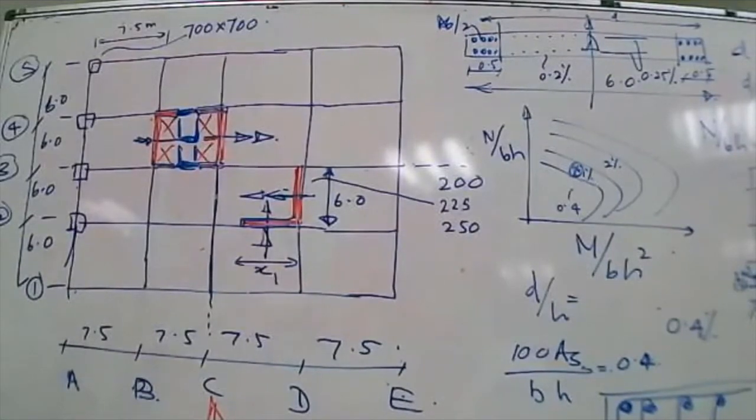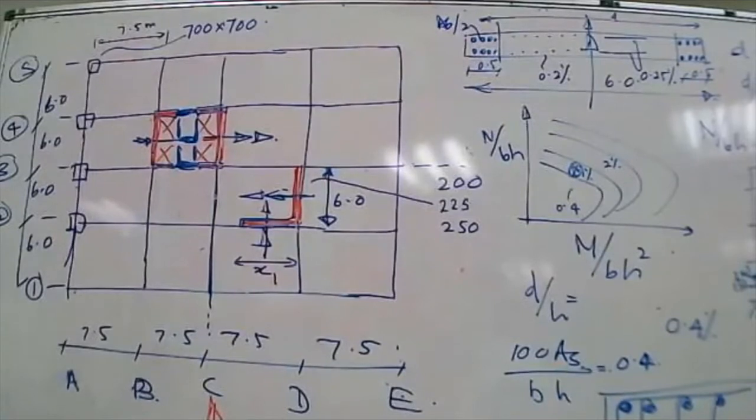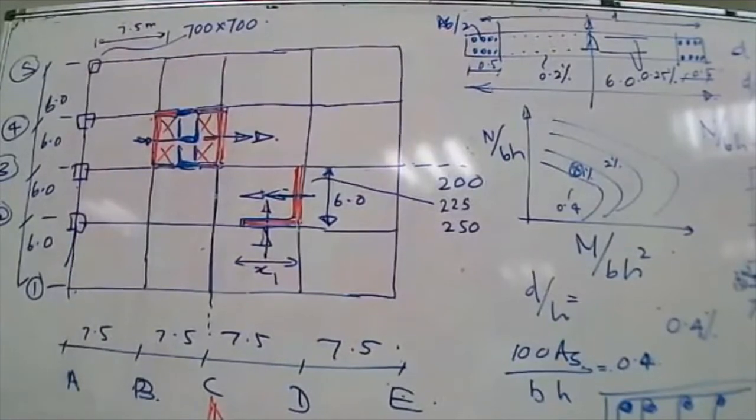Whereas when it comes to the structure, the architect should ask the structural engineer, what do you want? And then based on that only, the architect should do the planning, or the architect can do the planning with a flexible mind that the structural engineer asks for something extra because the building is twisting. The architect should be willing to give that option. Otherwise, it's too dangerous. There are buildings where the problems are persistent because the engineer has given in to the request by the architect. That is not the way.